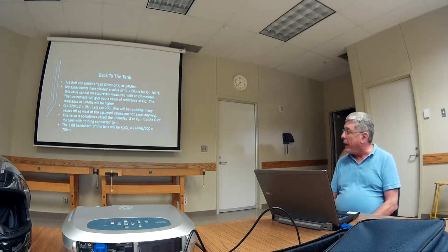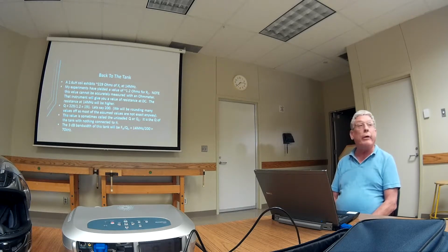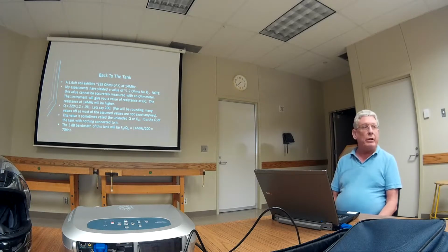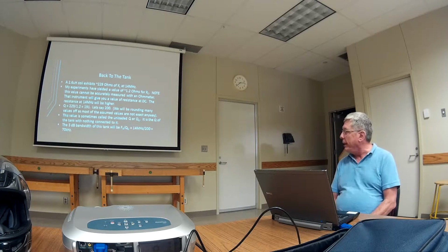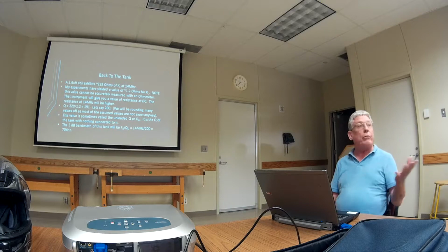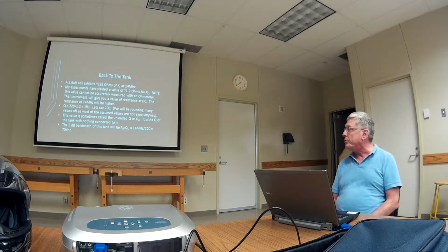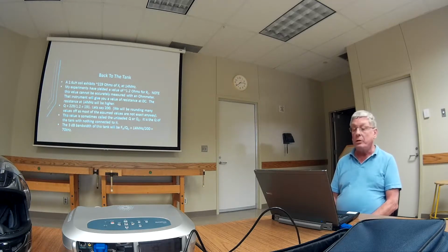The Q is going to be the reactance divided by the loss, which is 191. Let's call it 200. We're going to round off a lot of these values because a lot of this stuff is close, but not exact. This value is sometimes called the unloaded Q, or Q sub U. It's basically the Q of the tank with nothing hooked to it, just the tank components itself. The bandwidth for selectivity of 14 meg and a Q of 200 is going to give you about 70 kilohertz.